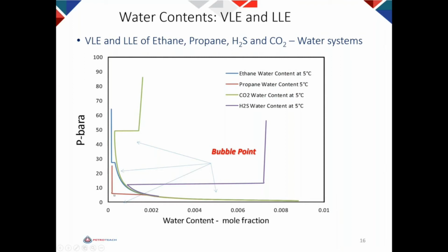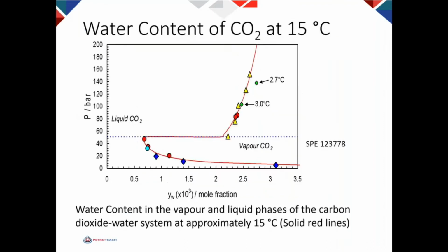And similarly for propane. But for CO2 and H2S, when they become liquid, the amount of water increases. So the liquid CO2 can dissolve more water. So this is the amount of water in vapor and liquid CO2. This is at 15 degrees.